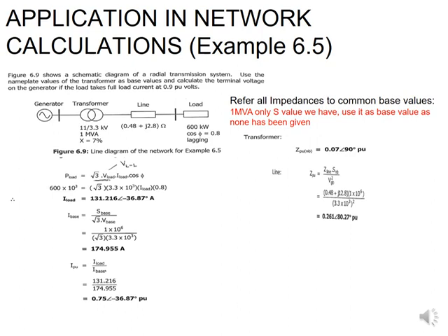Once I then have this, I can use the formula that says my V per unit generator is going to be equal to all of these other voltages together, because we know that when we're talking about Kirchhoff's voltage law, the voltage is going to decrease as we go towards the load until it gets to be a 0.